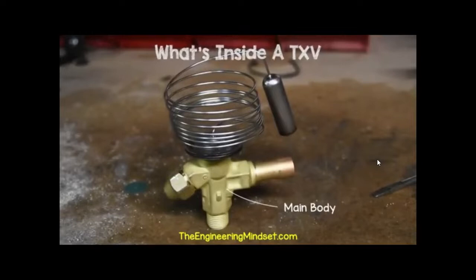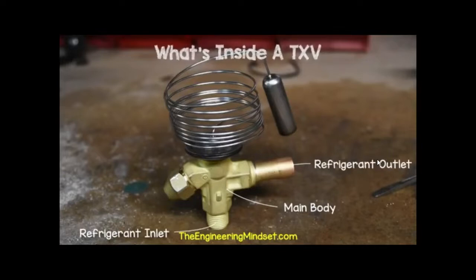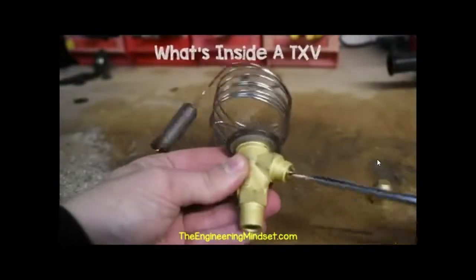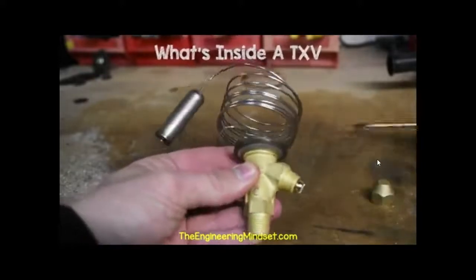In this model, which is a T2 thermal expansion valve, we have the main body, which is made from brass. On the body, we have the refrigerant inlet at the bottom of the valve, then the refrigerant outlet at the side. And on the other side, we have a cap which can be removed. Under that cap is a screw which is used to manually adjust the superheat.